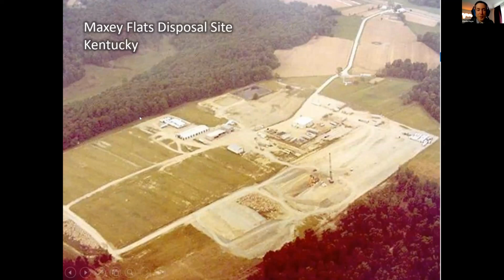So at one point, there were some monitoring stations set up. Tritium was detected in the nearby surface water, and at that point, the decision was made that the site would no longer be able to accept waste, and it was necessary to cover it and to stop the movement of contamination from the site. So when this picture was taken in the mid-70s, they had started that process. They had begun to consolidate some of the waste trenches. They had begun to treat some of the liquid waste that had been recovered from some of the trenches on the site, and they had begun to construct a cover to try to shed stormwater from the top of the site.